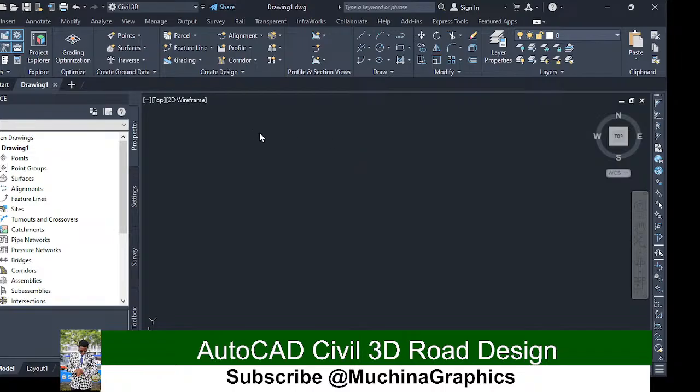When it pops up, I need to click import points. So I will click there, and then I will have this tool here. I click the plus button, and then I will choose my points. I will choose the topo survey points.